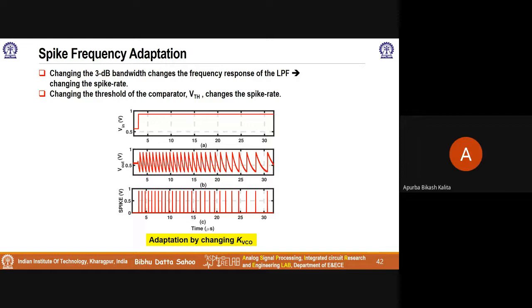Sir, regarding deep neural networks, can we just implement those deep neural networks directly through neuromorphic computation? We are implementing CNNs. You're not using this one, using capacitors. We are doing it. Yes. Right now, we are building a chip which can do capacitor-based addition dot product computation, and we are using a bunch of ADCs and DACs.